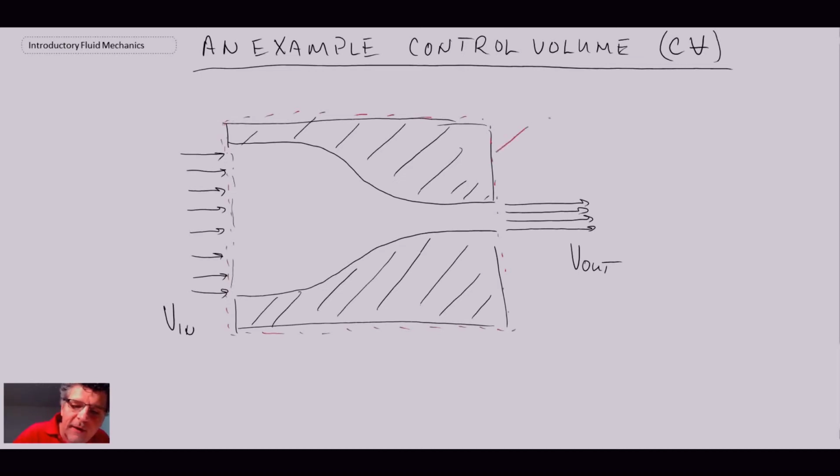You'll see we would do something like this to denote that that is the control volume. Another thing is that we have surfaces where mass is crossing the boundary. So we have one on the inlet and one on the exit. Sometimes we'll write control surface 1 and control surface 2, just to denote the fact that that's where the mass is crossing the boundary.